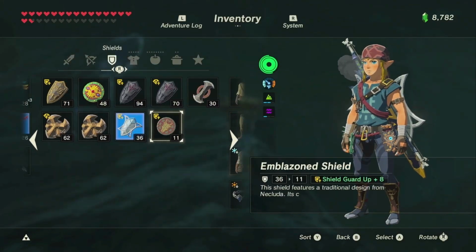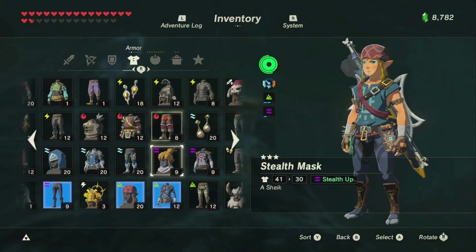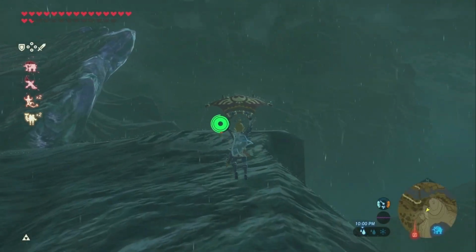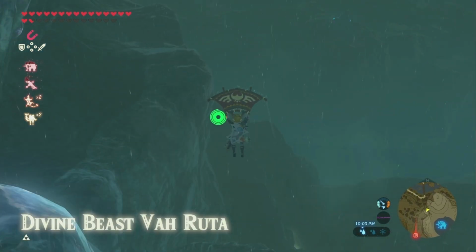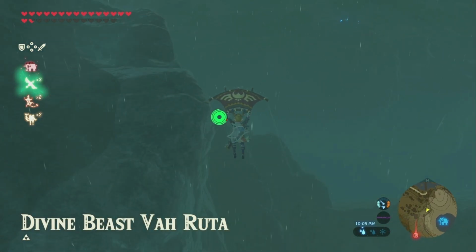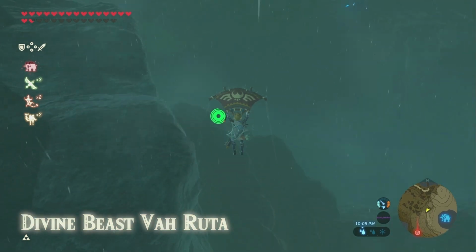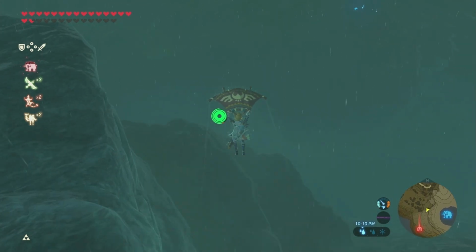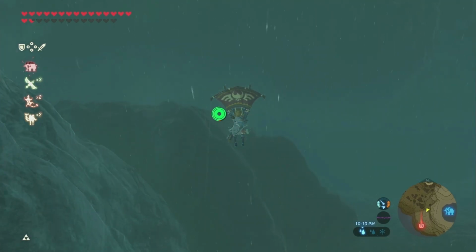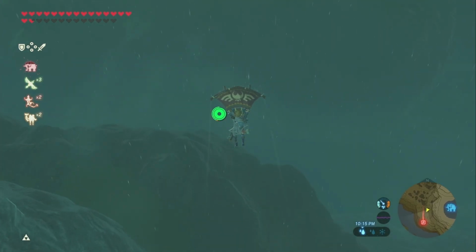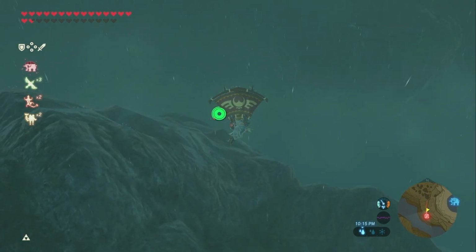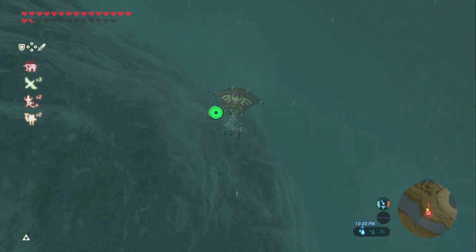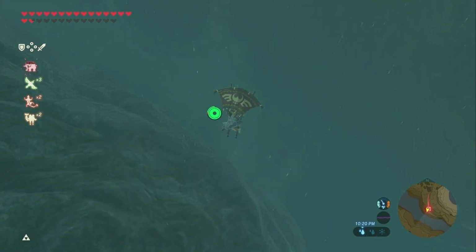For example, when the system is idle, the water in the hot water piping cools off. When you flow the first faucet in the morning, the cold water has to be flushed out of the pipe before hot water from the tank will reach the faucet. Yeah, it takes especially long during the winter. A circulating loop keeps all the water in the piping hot and eliminates the need to flush the system of cold water. For people who can't afford to wait 30 or 45 seconds for hot water, this is a necessity.